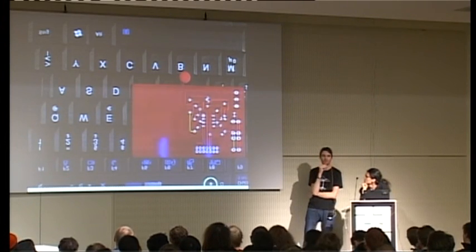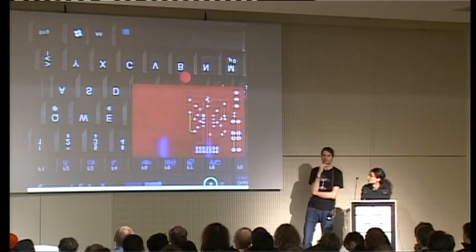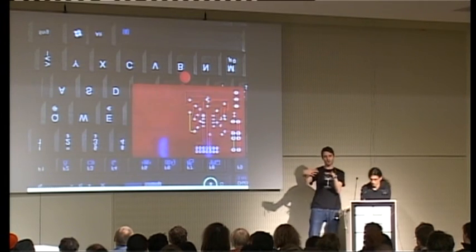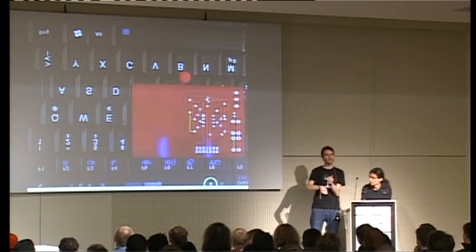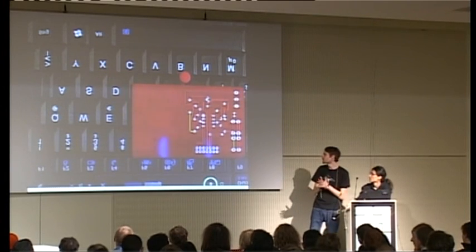One is thermal imaging. The idea is to use a thermal camera, and if you have a thermal image video, let's say, over the top of your PCB, then when you apply solder heat to any particular via or trace, you should see a heat signature through all of it. So that's one thing we're exploring.